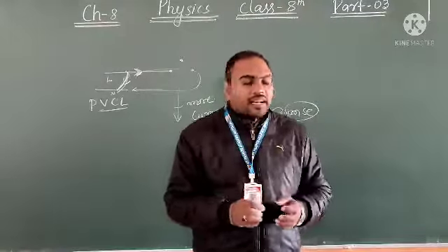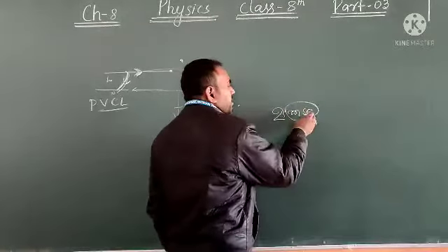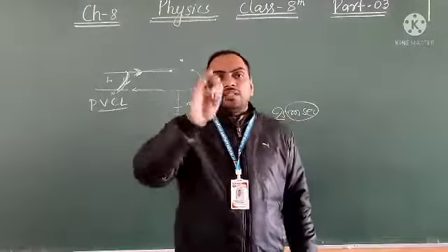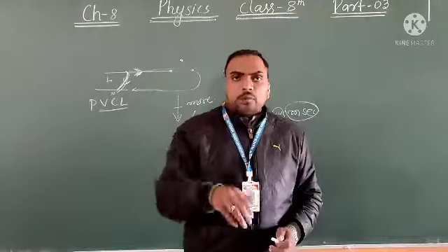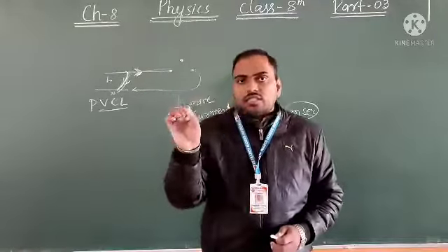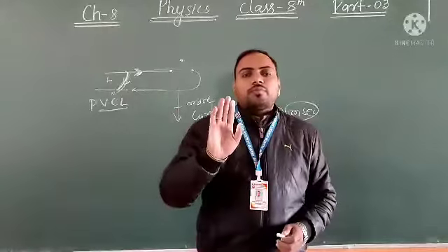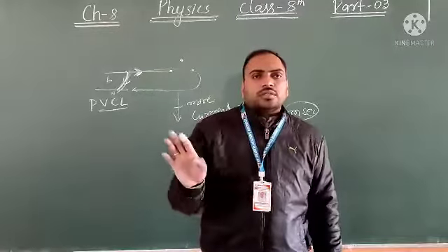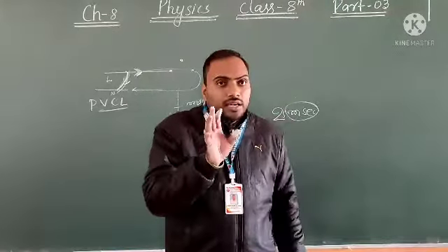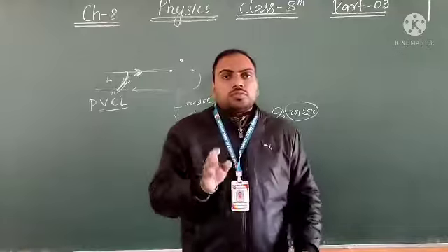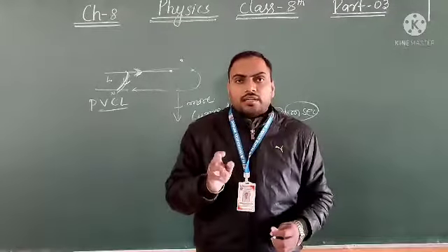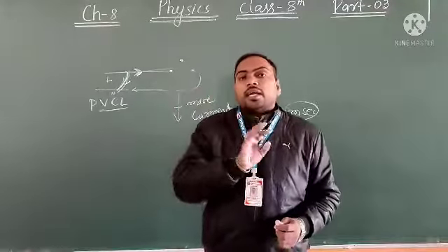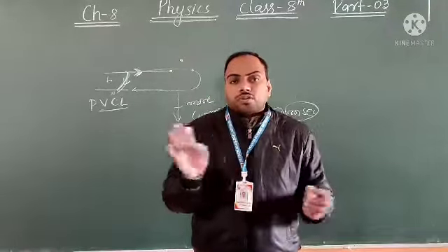When excess current flows through the conductor, through the circuit, it will trip. It will trip, and you do not have to change the fuse there. After the trip, you just switch the circuit back on, because with a fuse, after melting, after the fuse is damaged, we have to change that thin wire. In an MCB we do not have to replace anything.